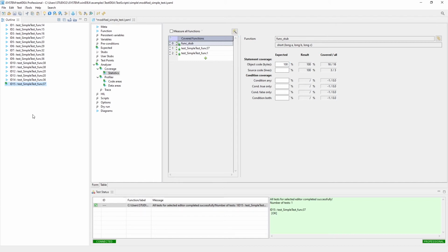collect between each step. We can step at about, depending on the clocks and stuff, you can execute about 50 to 100 instructions per second. So these microcontrollers are used to running in the megahertz, and you'd be running at like 100 hertz at the most or something. So if you do run in the slow run mode, it takes very, very long to execute just basic tests. So that's the huge trade-off.